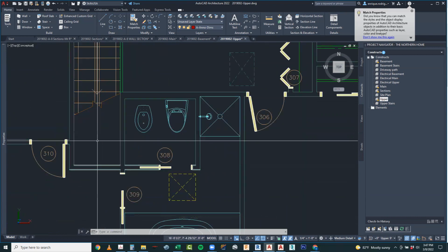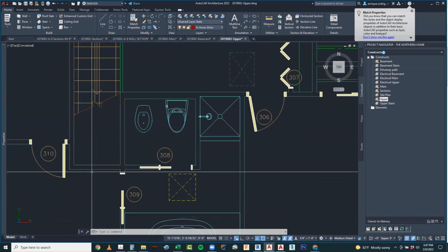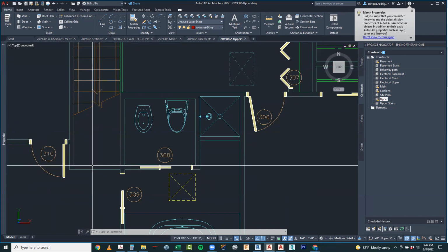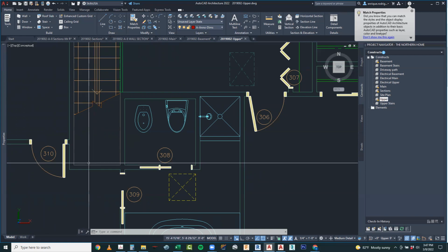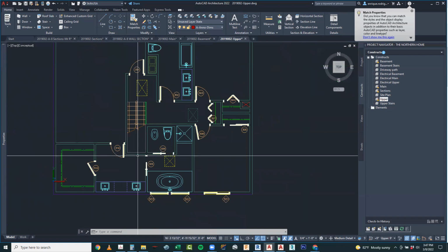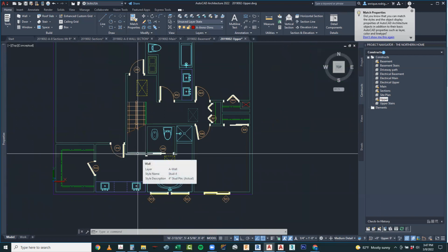And this wall is where the stairway goes under. So as you're walking down, you can probably put your hand up and hit that wall right there. What you don't want is for your head to hit it. Okay, so we got to make sure that we got enough head clearance at that point. The thing that we do have to find out is exactly where that wall is.